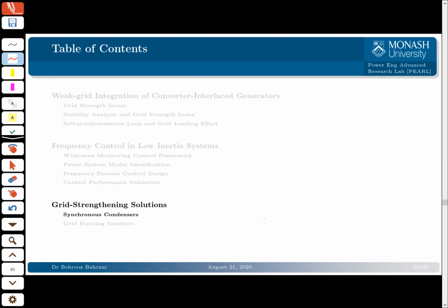But yet, these grid following inverters connected to these batteries are not really a part of giving you system strength, or they're not forming your grid. They are actually trying to help you to control your frequency, but they're not able to give you everything. So better than batteries that are in a grid following mode and are only, for example, reacting to changes in your power, it's better to use other technologies that can give you different services at a time.